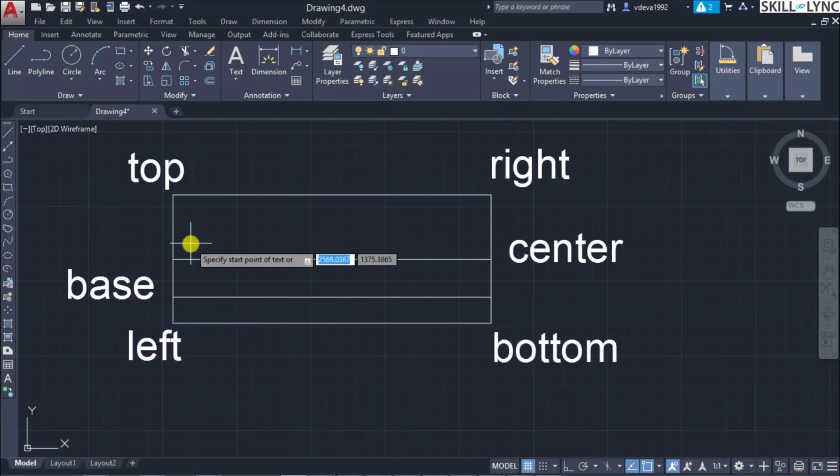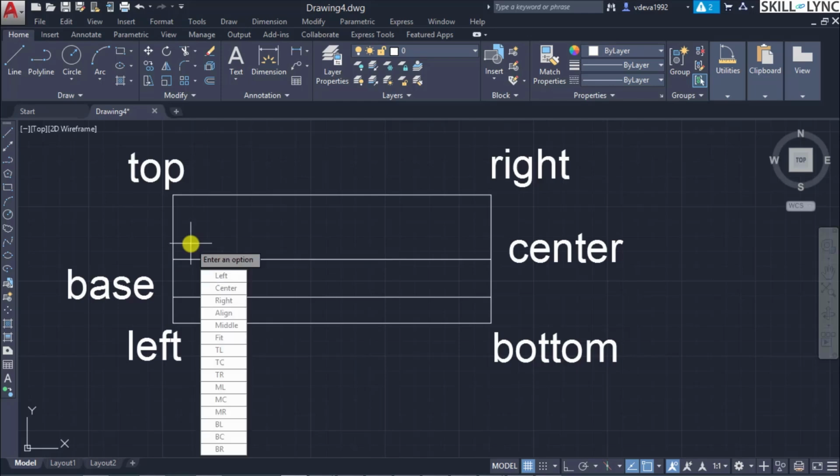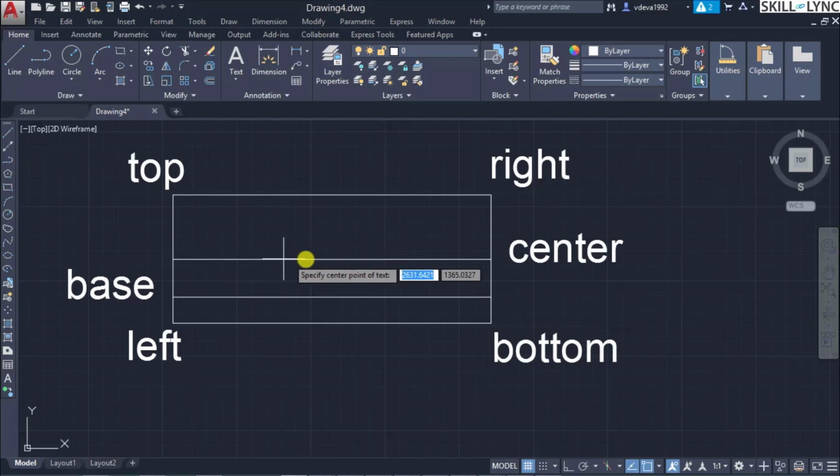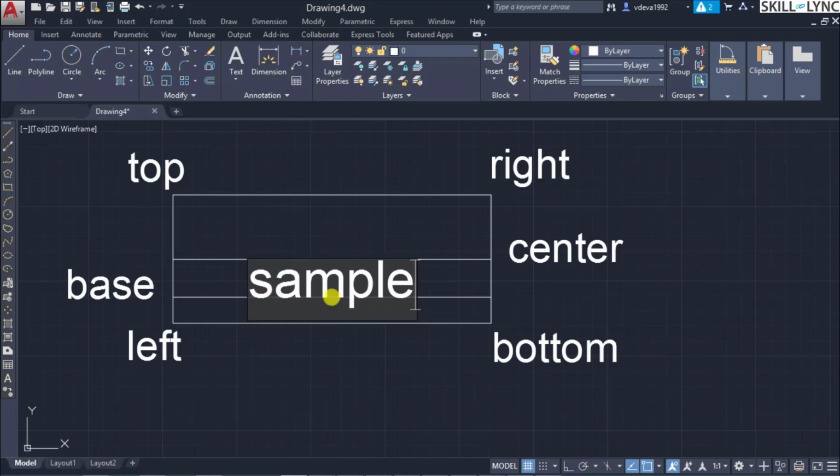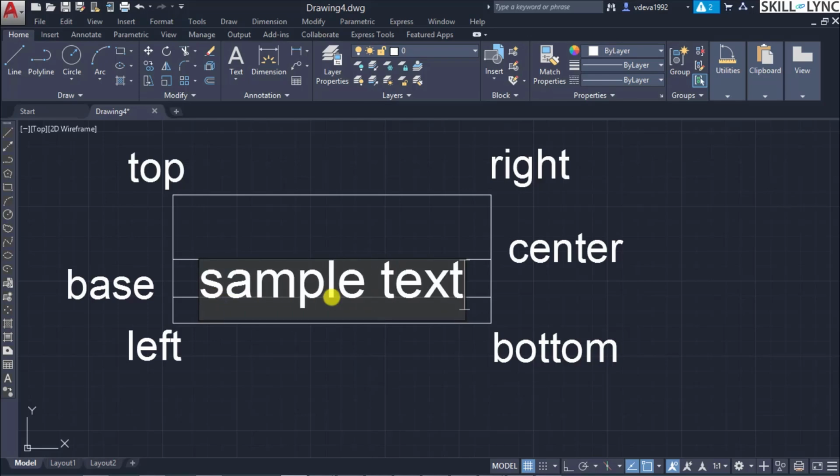Text, and then click down arrow to select the justify style. Next, let us go for the center align. So for understanding, let us keep the base point as here. Let us not choose the center line, but rather here the baseline. As you could see, which point we are selecting will be acting as the baseline. So just extrapolating from this center line to this point, that also serves as base. So specifying this and retaining the same height as 25, and then the angle of 0. Now let us type in the text, sample text.